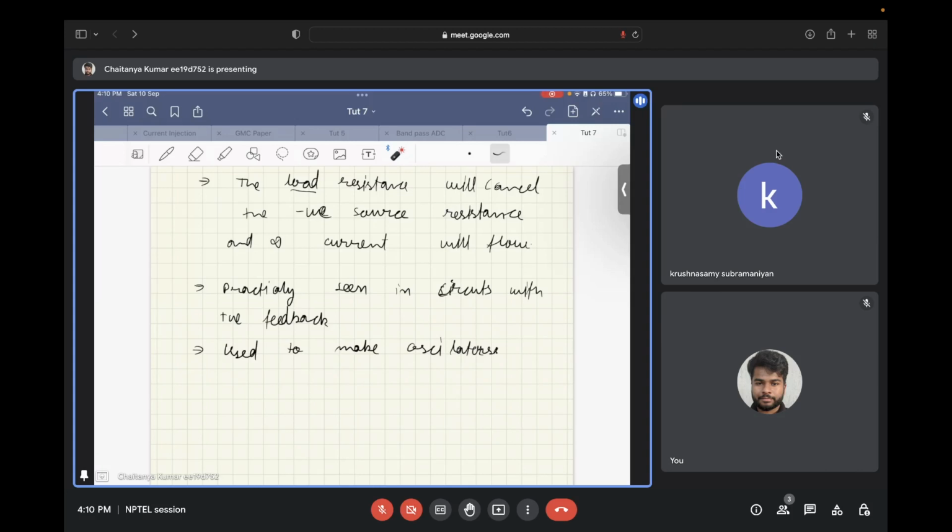What we want in oscillators is positive feedback. The concept of an oscillator is that it should be able to give you some power at some frequency without any input source. Basically, the input is zero and the power output is some particular value, so the power transfer is effectively infinite in this case. That's how oscillators work. Under certain circumstances, we can put a huge amplifier in positive feedback and generate these negative resistances. Any doubt in this?